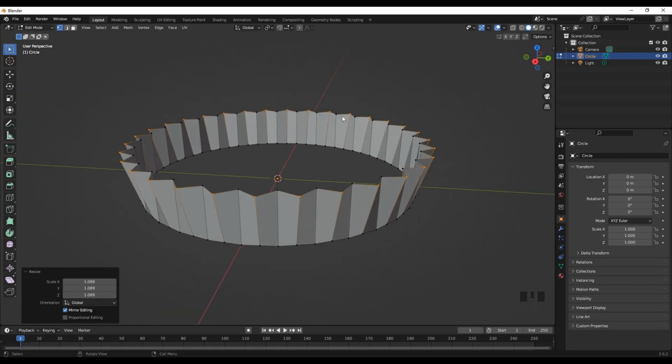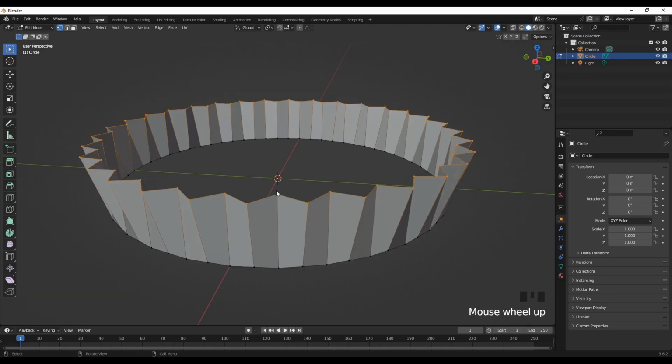Okay, now it's time to extrude this further. We are modeling the holding cup now. All right. So hold Alt and then click on a specific vertex, and this operation selects the entire loop of vertices along this one.